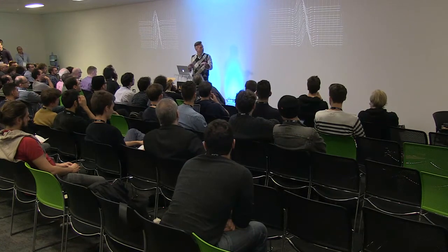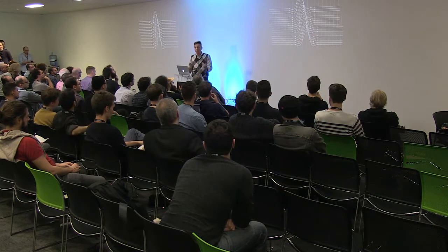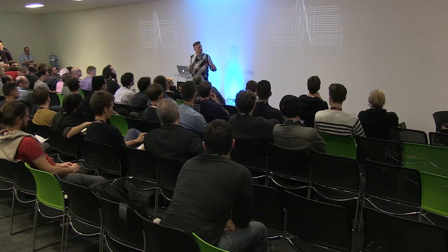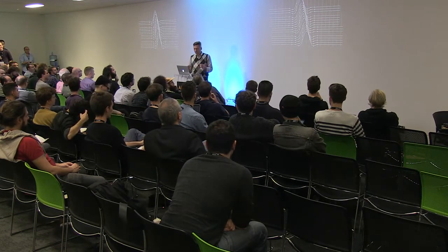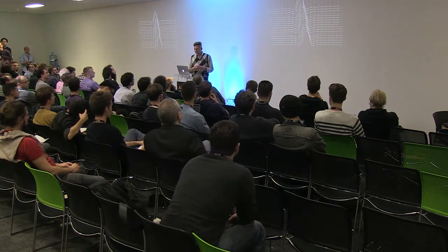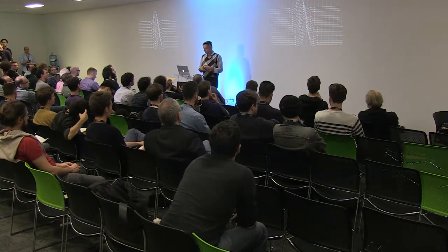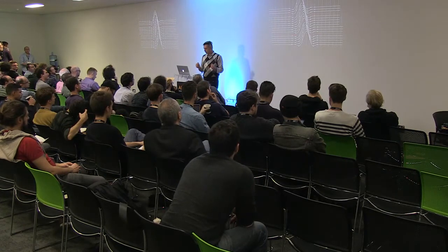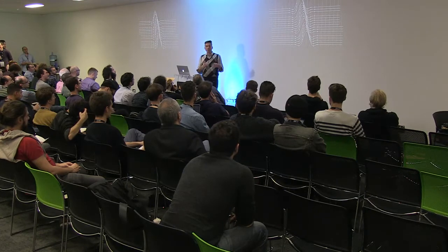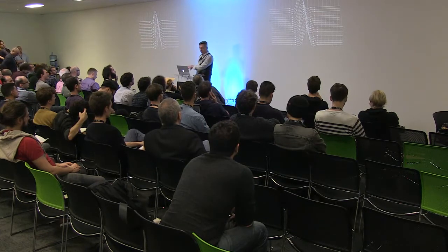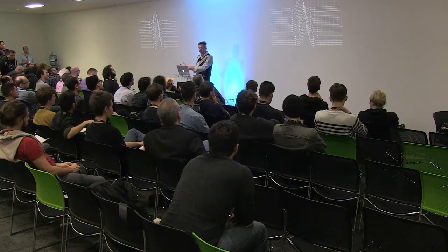Just throw all like 16, 8, or however many samples you have per blit into that, and you're set. The thing about this is, if you implement that, you should have a producer of those blits that puts them into some delay line, and a consumer, which is an integrator.